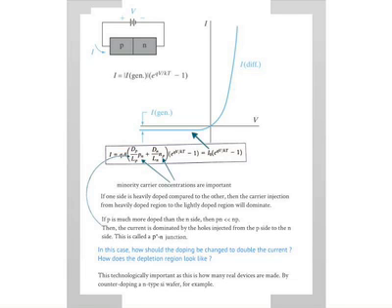Or another way to think about it is that once the electron comes here, it's diffusing and recombining at the same time. Now, for it to recombine, it needs extra holes. Those holes recombine with these electrons, forming a bond. Those holes can also come from the thermal generation, electron-hole pair generation. Those are the excess holes, so it's also called a thermal generation current, as shown here.